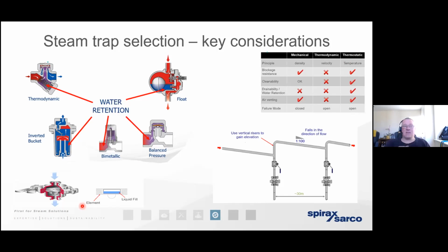And when we've got a thermostatic trap that's used specifically on a clean steam system, it's going to have a specific element that is very, very sensitive, and it will open very, very quickly to ensure that condensate is drained away as soon as it is generated. So it's a very, very sensitive trap. You'll also notice that unlike a plant steam system, we don't have a dirt pocket because by nature, we're not going to have any debris or particulate on the clean steam side of the distribution pipework. And we want the condensate to fall straight through the trap where it can be taken away straight back to the energy center for reuse.